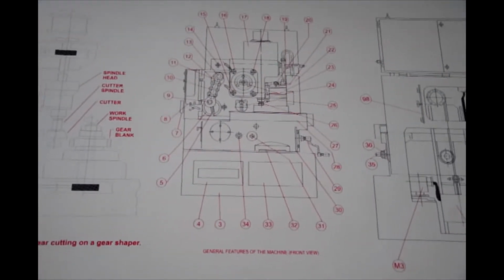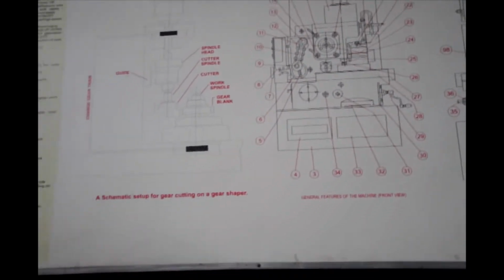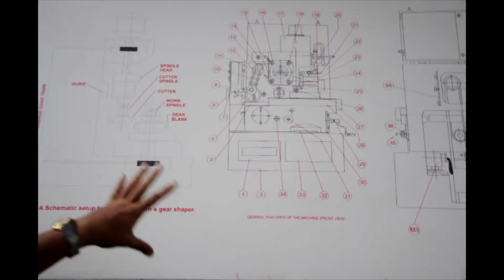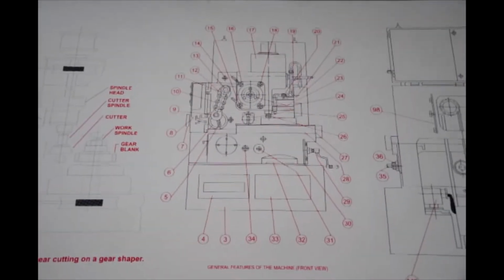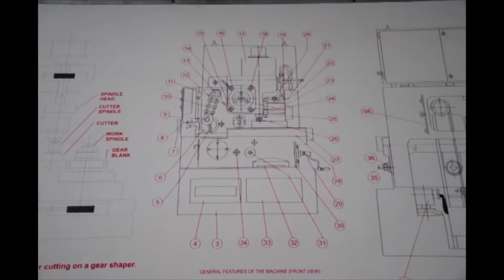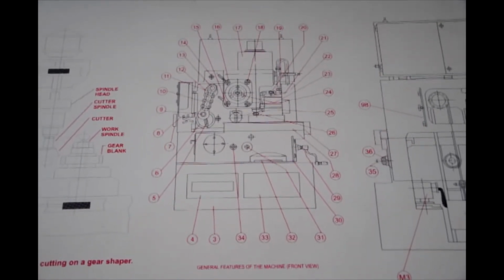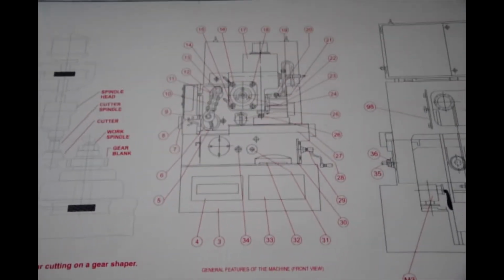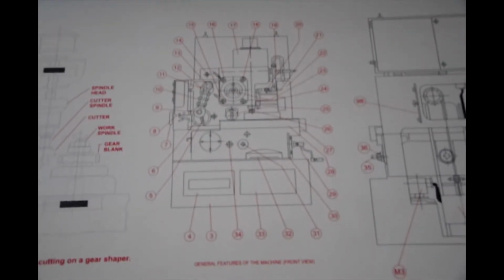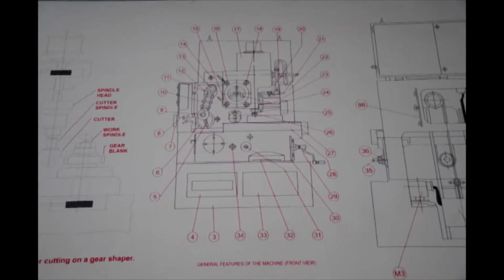We have shown the external gears, and similarly internal gears can be cut. These are complex mechanisms where, through one single rotation from the motor, all those index rotations and the reciprocating action of the gear cutters will be implemented. As the gear cutters reciprocate, that is why it is called a gear shaper.